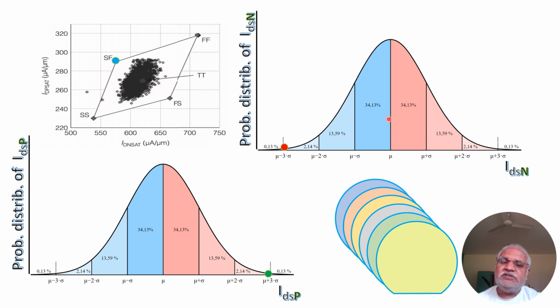Then we will know how the first version of the silicon implementation in the fab is working. Based on that, further tunings are done in the next steps of the design: if small corrections need to be done, through ECO, or through a few layers of metal change, or through a full all-layers mask change.